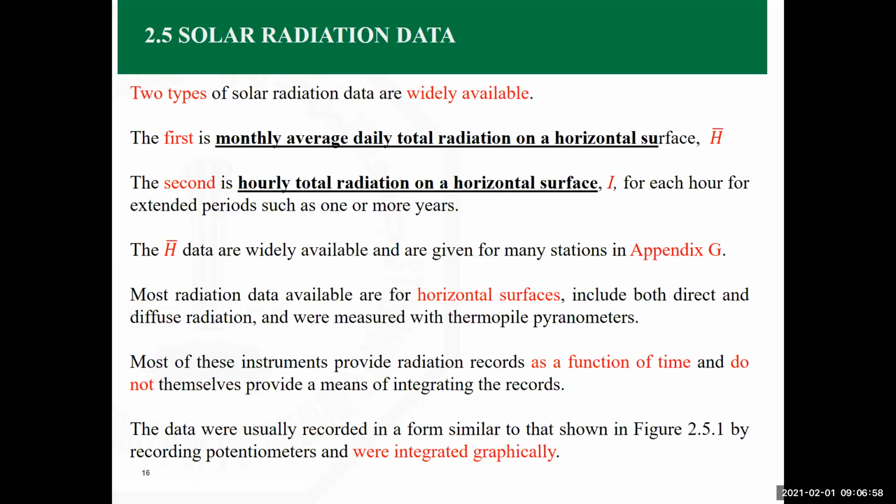Actually, you may have a pyranometer, and the pyranometer could be connected to a readout. This gives you instantaneous values on the spot, how many watts per meter squared. But the instrument itself can have a way of storing the data, or it can be connected to a data acquisition system so that you can store all the instantaneous values over a certain period of time. And then if you wish to get averages, what you need to do is to integrate over the hours.